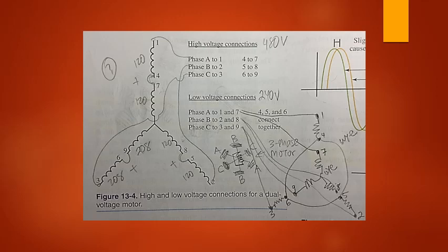Consequently, in most motors, the rotor travels slower than the synchronous speed of the stator. The difference in these two speeds is described as slip. Generally, slip equals 5% of the motor's RPM. A 4-pole motor with a synchronous speed of 1,800 RPM would have an actual speed of about 1,725 RPM due to the slip.